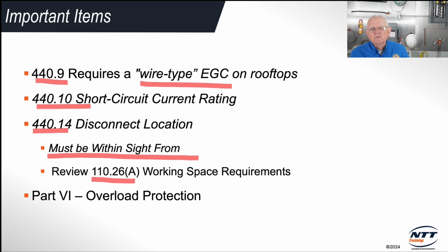Typically that's not a problem, certainly outdoors. And the height of the working space. So you've got to have enough room, that's 6.5 feet, so you can get in there and not hit your head. Once again, really not an issue when we're talking about these outdoor and rooftop condenser units. Also remember, that reminds me, on the rooftop units, you're required to have a receptacle within 25 feet and on the same level of that rooftop unit.